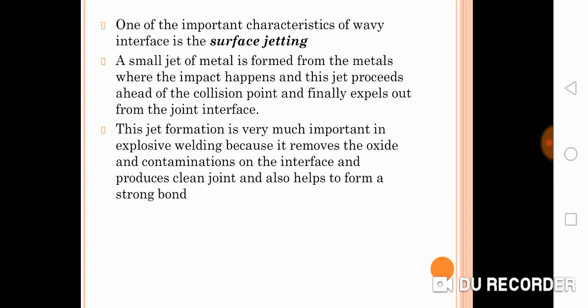That means whenever two metal plates come and hit together, in front of the collision point, where the two plates meet, you can see a metal jet forming.